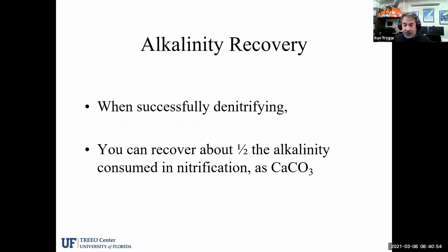An interesting thing with producing nitrogen gas from nitrate, we will actually produce some alkalinity in the form of either carbonate or hydroxide alkalinity when we successfully denitrify. And remember, we said earlier in this discussion today that we talked about nitrification, and we said alkalinity was a huge part of nitrification because we were going to use up so much of it. There was like 7.1 parts of alkalinity used per 1 part of ammonium.